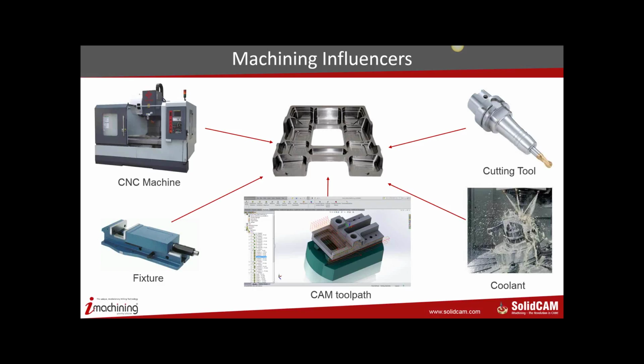The other reason why collets are a big no is because when you're cutting titanium and when you're cutting Inconel, you generally tend to use high helix cutters. And high helix cutters, when they come in contact with material, the material has this ability to pull the cutter out of the holder. So your clamping force on the tool has to be extremely high, and this just cannot be achieved by collets. If you're going to use a collet, trust me, in the very first cut, the tool is going to be out of that collet. So you have to use suitable holding devices for the tool.